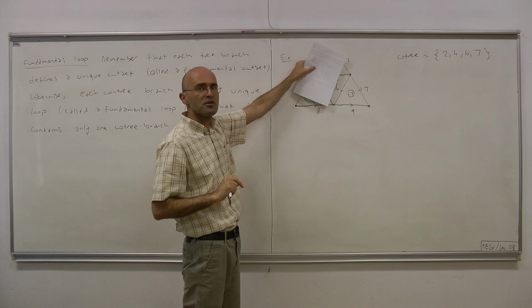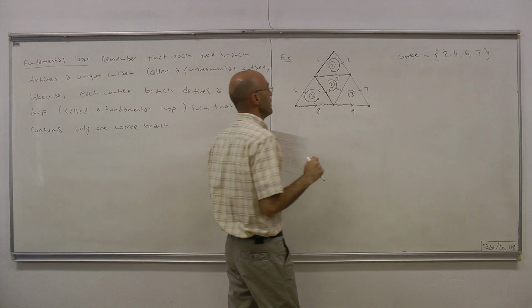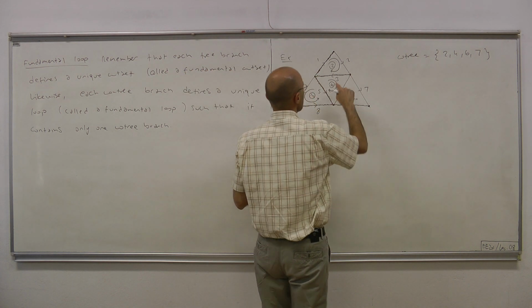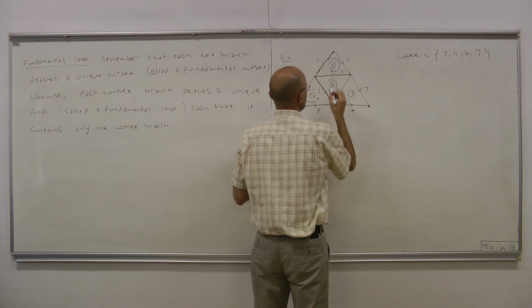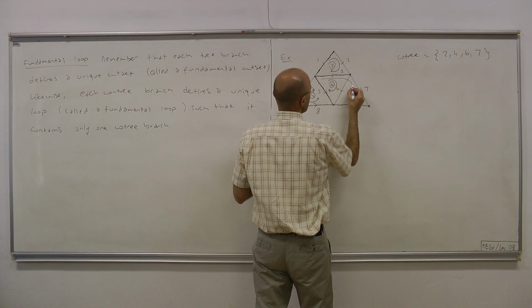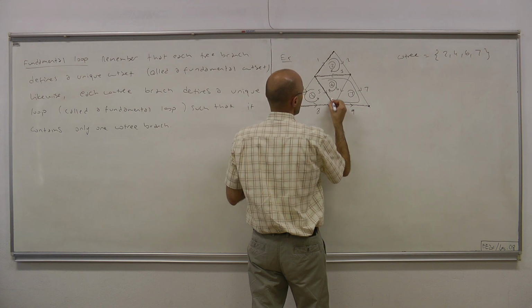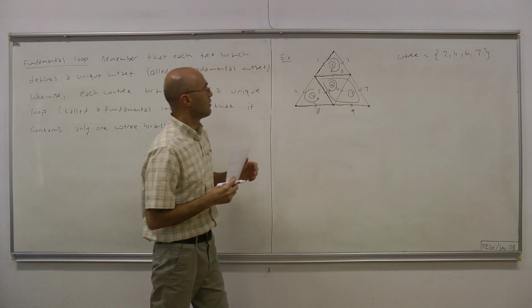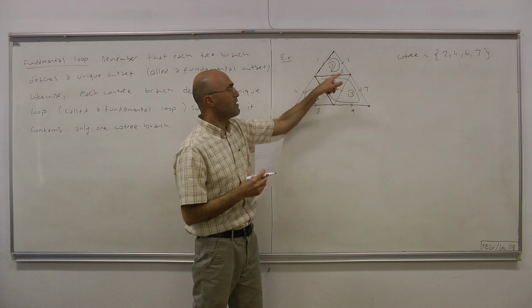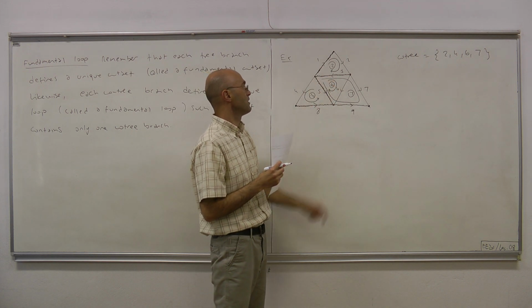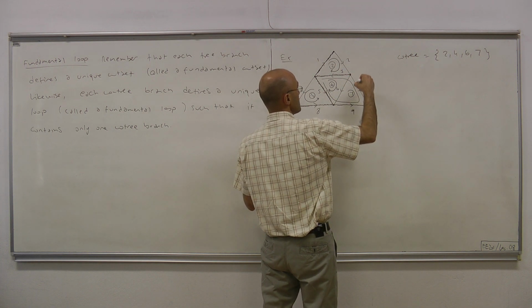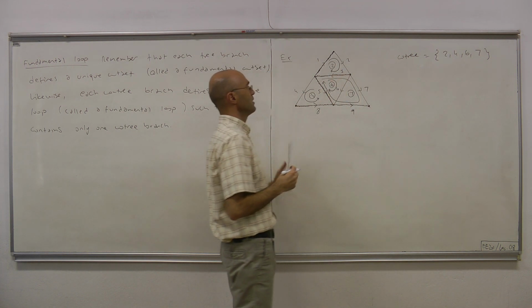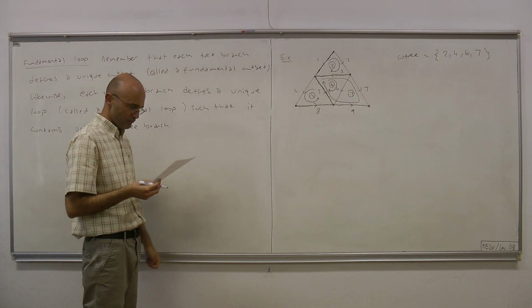All the remaining branches must come from the tree. If you apply that constraint, then you see that this must be your loop 7, 9, 5, and 3. Because 3, 5, and 9 are tree branches, and the direction of this loop must be the same as the direction of the cotree branch 7.